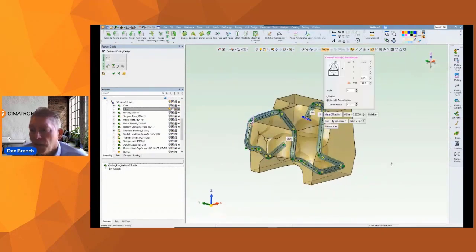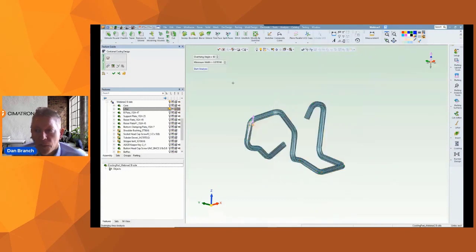And I can actually have the same function while I'm designing, do some analysis on the channel. One of the checks I can run is an overhang analysis. I mentioned downward facing surfaces are not good, but as we can kind of assume, they're unavoidable. So what this does is it measures the ramp up to those downward faces. The printing machines can make the next layer of material okay if the angle is slight enough. So here the triangle section is a good one to use, and I don't see any problem at 45 degrees. But if I change that ramp up angle to 60 degrees, then I do get some yellow areas, and those would not satisfy the condition. So maybe I make some adjustments to the channel or to the twist.